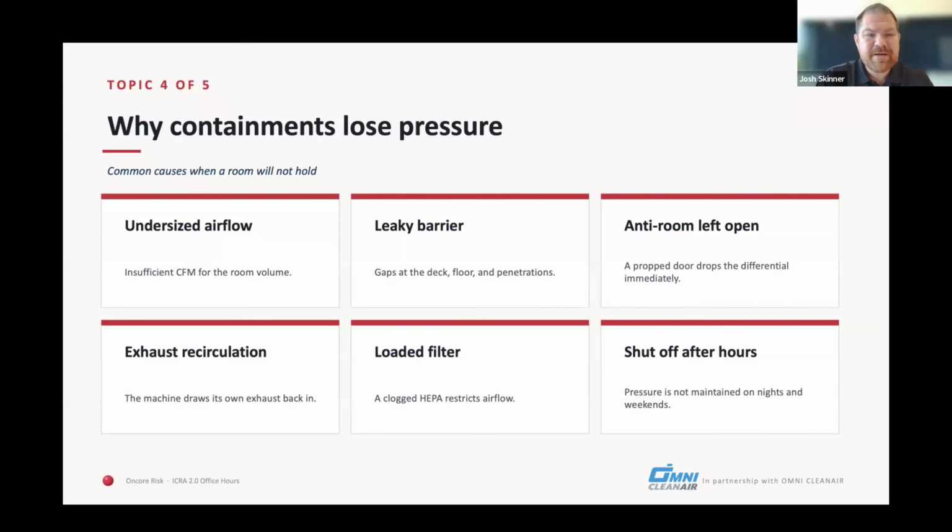Fully agree. I think if we were to use simple context, between 0.08 and 1, you're getting the yellow, and above 1, you're getting in the red space. You're getting really, really dangerous for potentially affecting everywhere else around you. And the whole point of what we're trying to do is to not affect all the space around us. Between particle sampling and maintaining, literally the whole goal, even using a good temporary wall, is to make sure that we have an unaffected space surrounding the containment space. Yeah, I've seen spaces at 1.5 inches, and I'm like, why are you doing this? And it's the old adage, more is better, but really it isn't.